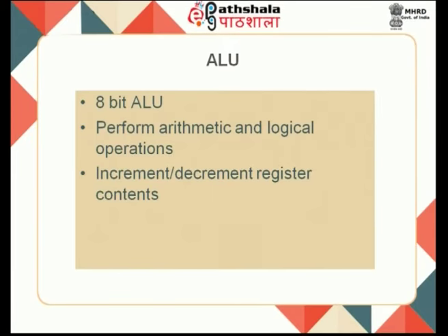It will send the data to one particular temporary register, and from there it will go towards where we wanted to have our results. When I am looking at a multiplication or division, by the time people will put the operands in the accumulator and B register. So, it has been confirmed that before doing this operation, your data should be moved towards A and B. Here A refers to the accumulator. So, the arithmetic operation is done and the results will be taken out.